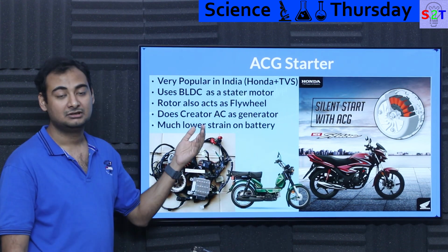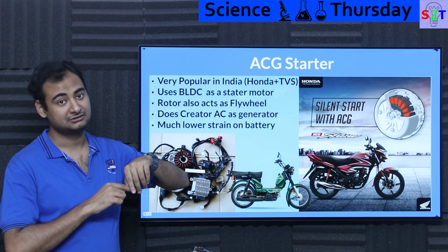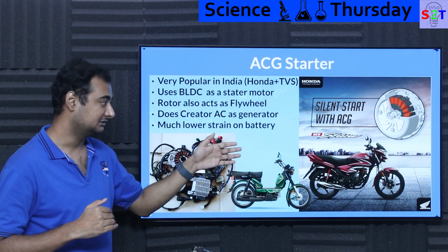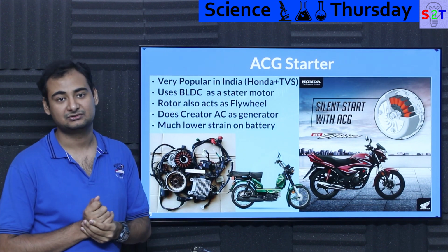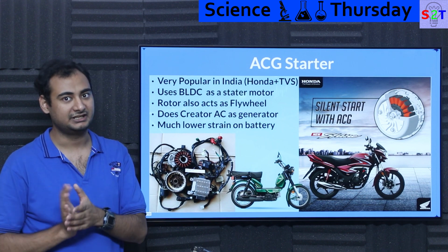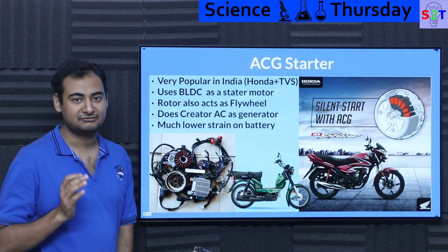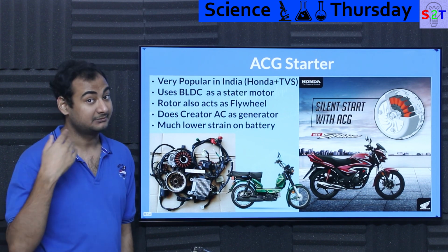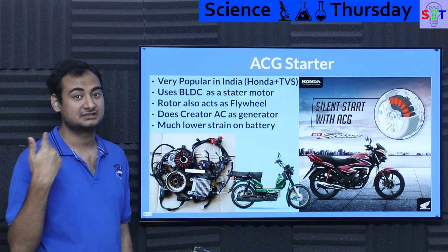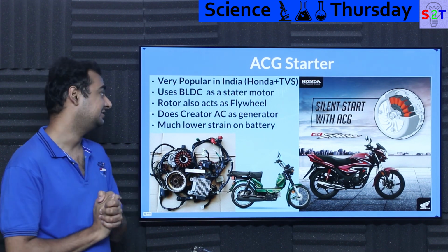It does create AC, you have to be very mindful, and it does have that issue of ludicrously high voltage range. So at, let's say, idling RPMs of 2500 it is awesome, but the moment you floor it, it will go very high, and the inverter unit, this brain, has to be smart enough to say, whoa, voltage is going too high, either dump the energy somewhere or just disconnect it. Not relay disconnected, as in float it in IGBT.